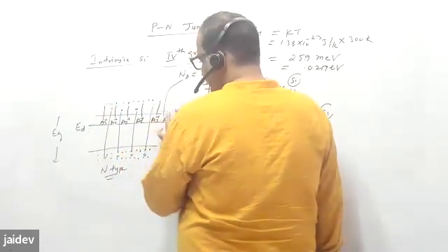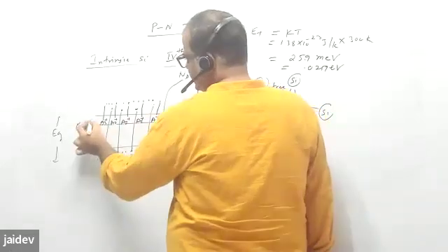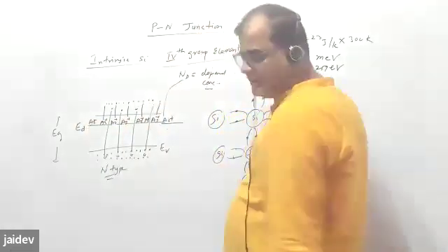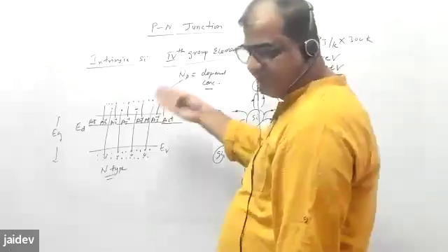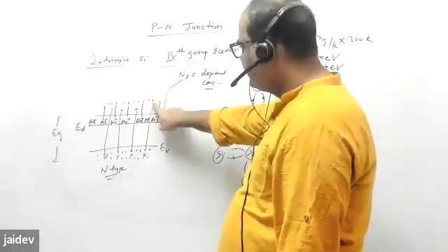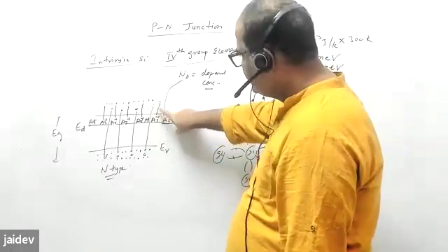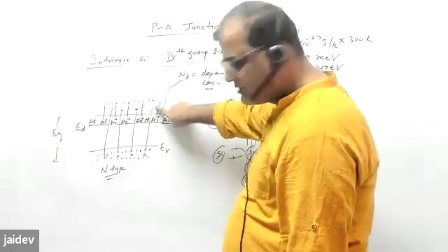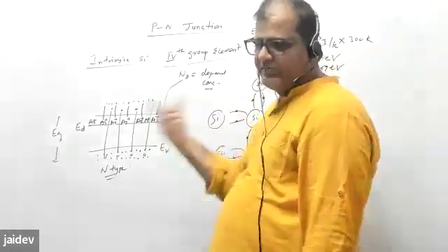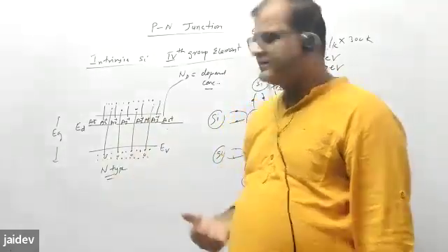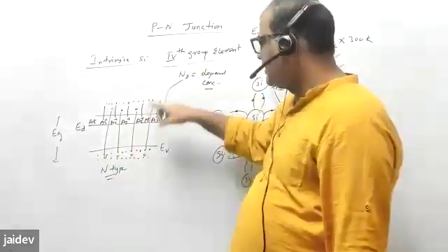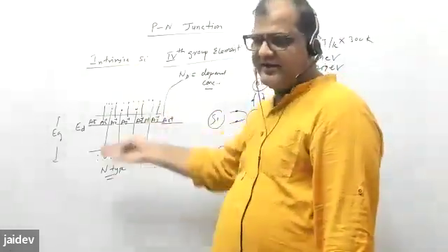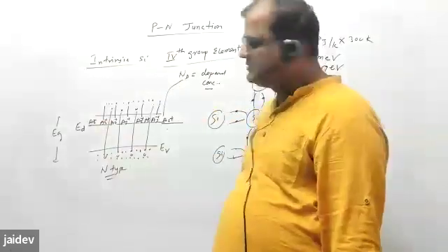These are arsenic atoms. The dopant concentration is 10 to the power 10, 15, 20. The intrinsic number here is 10 to the power 10, while this number may be 10 to the power 12, 13, 14, 15. So compared to this number, those numbers are very small, and you can neglect 0.1%, 1%. So this number will dominate. Now you have a lot of electrons, and this is ready for conduction. This is the example of an n-type semiconductor.